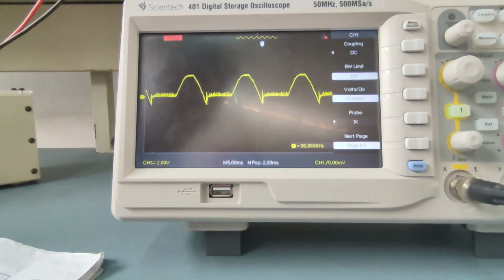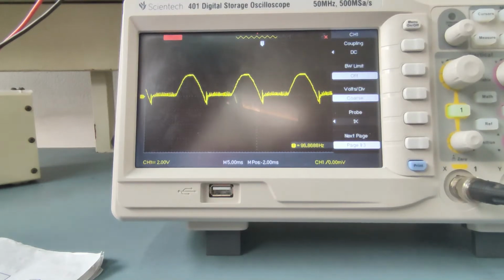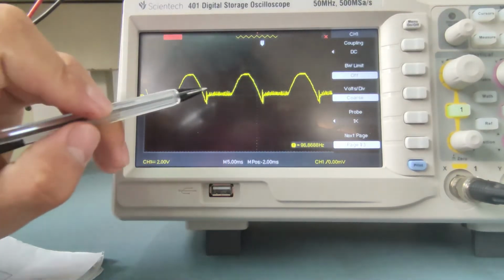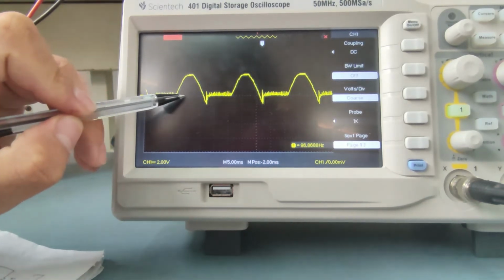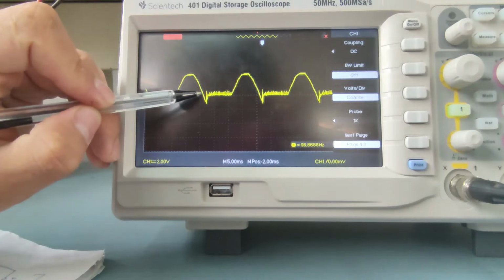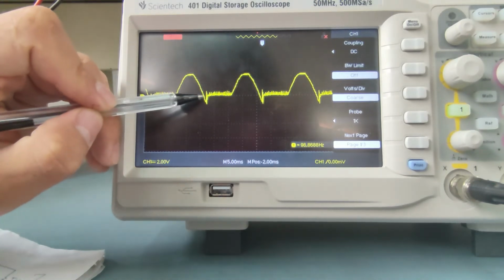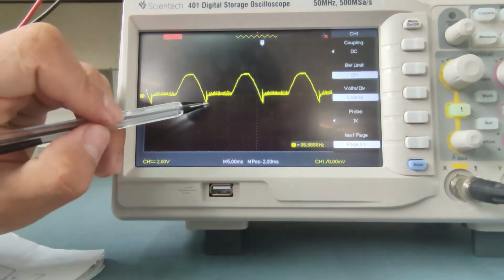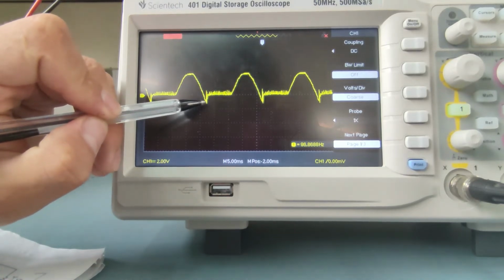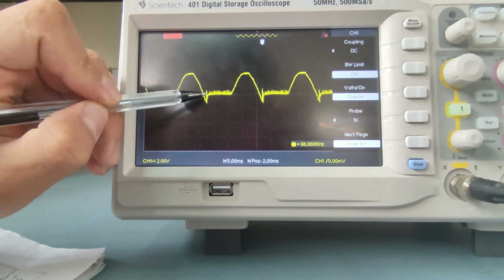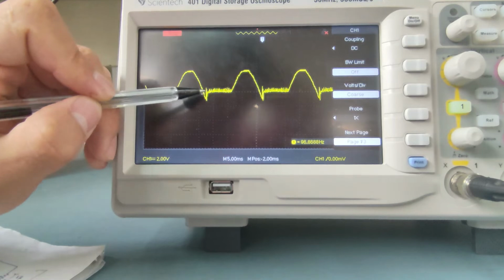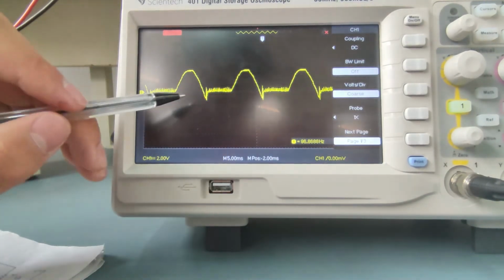And when the supply voltage is 0, the current doesn't fall to 0. As a result, the diode will keep on conducting even for the negative half cycle, and we see that this is the zero baseline, whereas for the output voltage we see that there is some voltage being registered in the negative half cycle. At this time t, we see that the current is 0, and as a result there is a negative voltage registered in the output of the RL load.